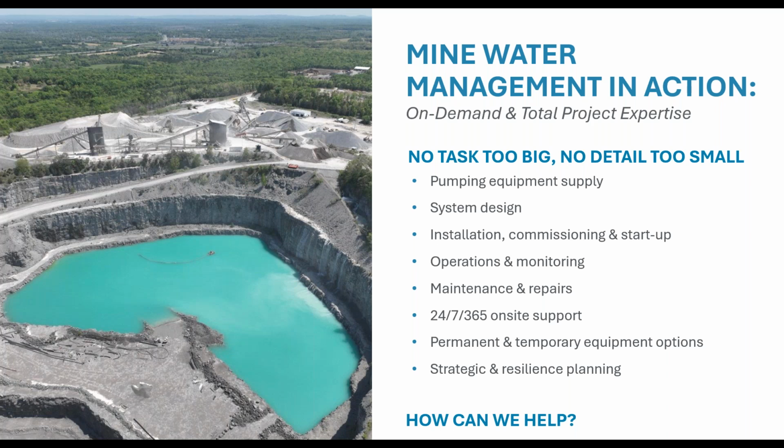It's a great question. So the first thing, as I mentioned, there were custom sumps that were strategically fabricated and located at the low points where water was collecting. The fabricated sumps helped to mitigate some of the sedimentation that was being experienced in just a traditional in-ground sump. The Flygt MSHA pumps that were utilized in those sumps have hardened impellers, so they were able to handle some of that silt and sediment that was being experienced.